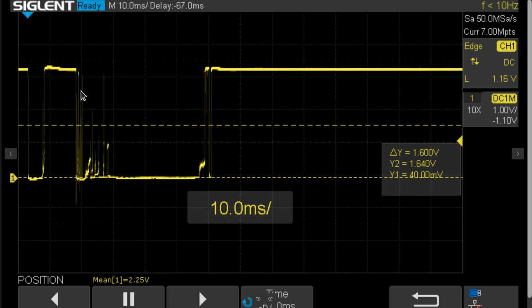This one is really bad, by the way. We're going to have to set it to like 20 milliseconds to not falsely trigger here, and to not falsely trigger up and then down again over here. So think about this, right? Wait for 20 milliseconds and make sure you're stable. Oh, I went unstable. I'm not stable anymore. Okay, reset over to here. Now I'm back to where I was.